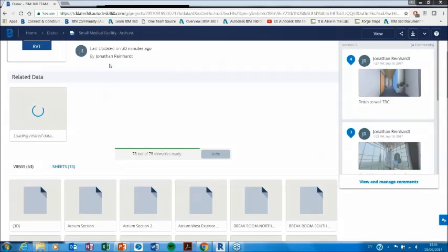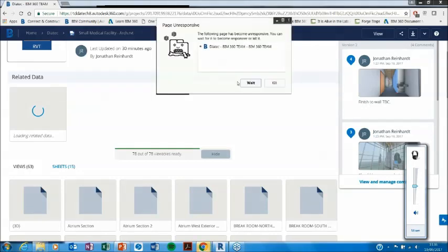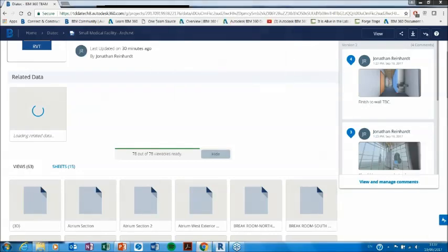Mark, anything to add there? No, I mean, just in terms of downloading models, and the different levels of user permission. Yeah, so you control the user permission when you invite somebody. I'll just go into it now. So I'll just close my Revit in the background here. When you invite somebody, you can set whether they're an admin or an editor or a viewer of a project. So you can assign that as soon as you're putting their name in. So it's quite flexible.